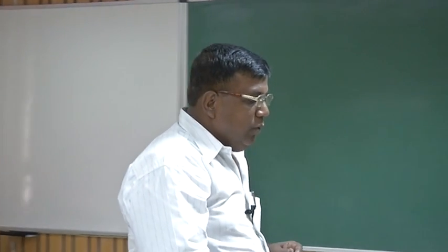Morning, we were discussing stability and control of an airplane. More explicitly, we were trying to understand the relationship between stability and control. Using common sense, we understand that if a vehicle is statically stable, and I go on increasing its static stability, then to change its equilibrium from one known equilibrium to another, I have to apply larger effort, because since it is highly stable, it will always try to stay in that original equilibrium point.